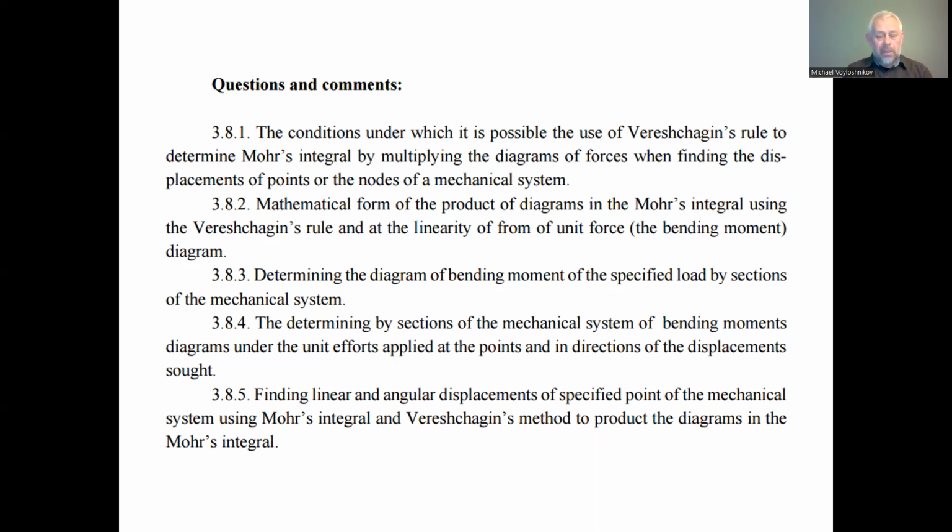We can decompose these diagrams into simple forms, triangular or trapezoid, but usually triangular. A trapezoid diagram of the bending moment we can transform into two triangular diagrams, and for a non-linear shape, we can likewise approximate the parabolic or other shape of the segment by the trapezoid form.